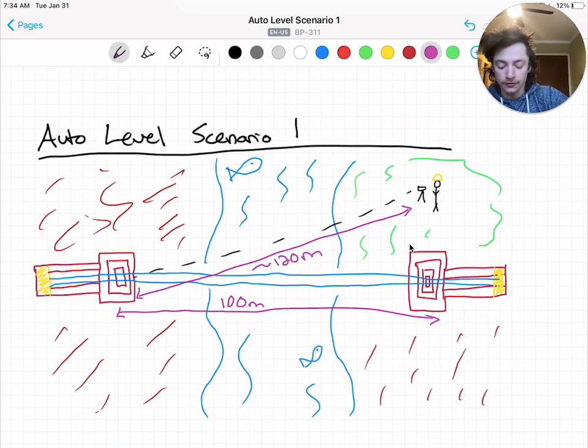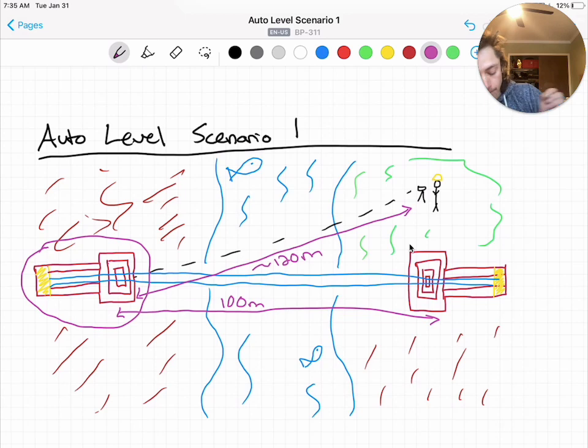So I have a wonderful photo or diagram drawn for you here. The marks would be, say, on this abutment here on the left. And I've drawn out the potential dimensions that we would see. So let's consider this scenario for a 100-meter bridge. Because the bridge span is 100 meters, we can approximate that you're about 120 meters away from the tiers as you're sighting it by standing off to the side over here, of course, wearing your hard hat.